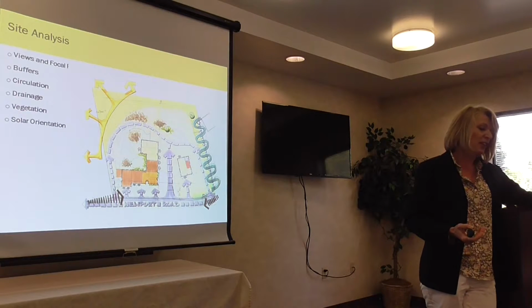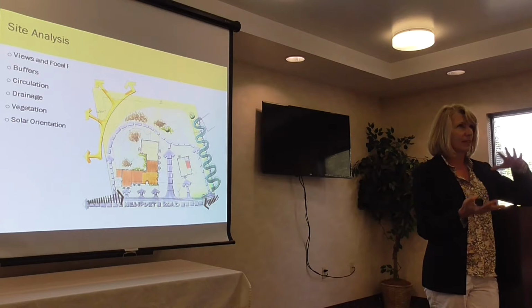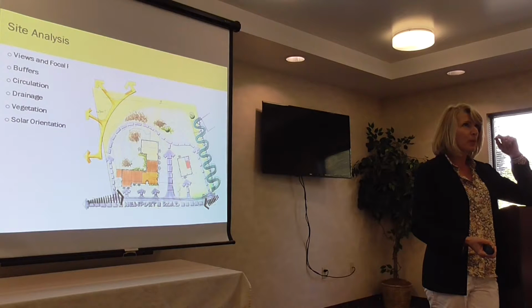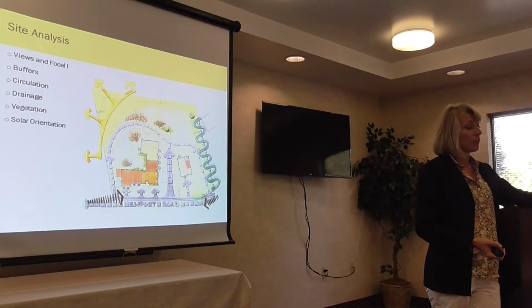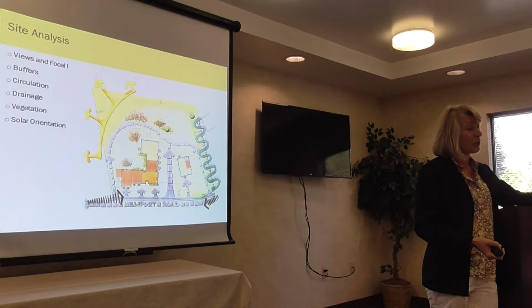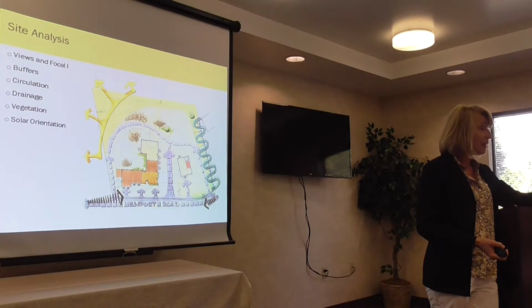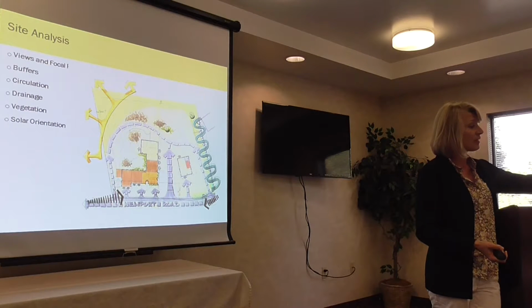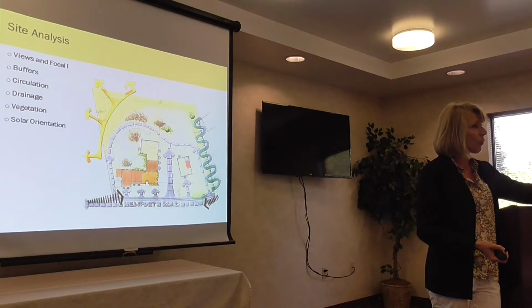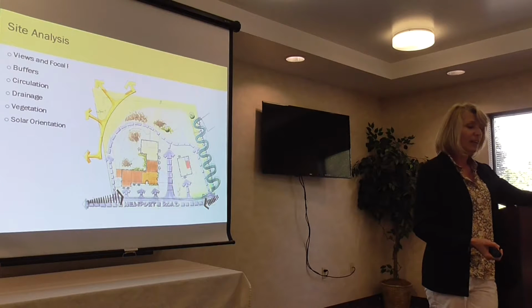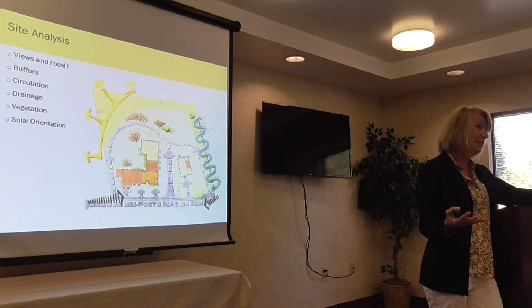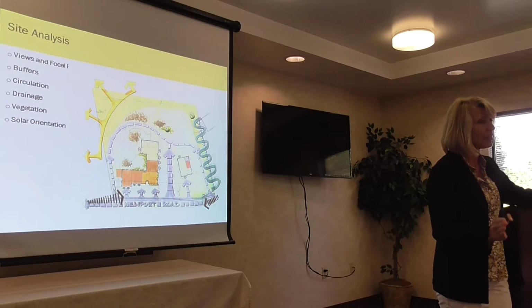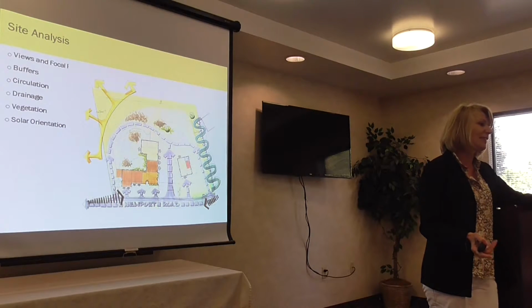Vegetation, what types of vegetation, and depending on the project, this can get to be pretty detailed. We'll get down to the different types, especially related to invasive plants. If you have a really infested section of vegetation, you're going to want to mark that, identify that. If you have an area that's pretty pristine, a really nice area, I want to set it aside, I want to protect it, identify that, because that goes back to protecting those areas.